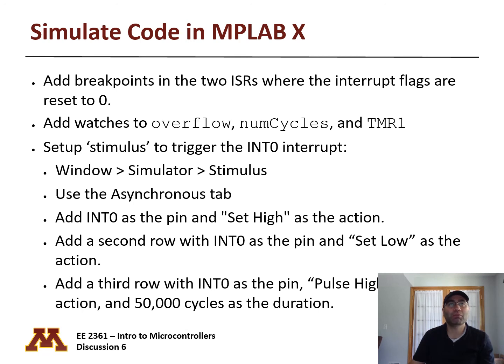We want to watch these variables, so add watches to overflow, number cycles, and timer 1. Then set up a stimulus to trigger the INT0 interrupt. I'll do it in the video, so if you can't do it, you can watch that part of the video. And then go to stimulus.